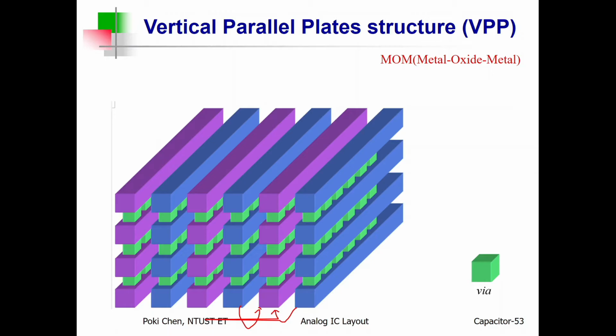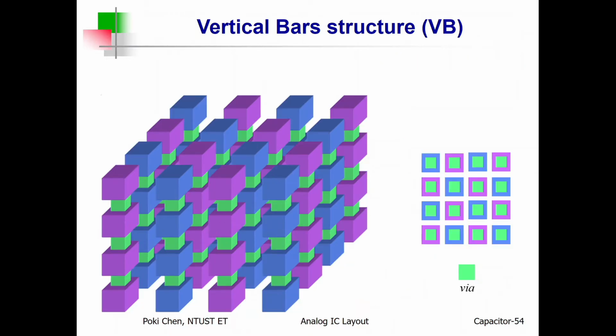Almost no electrical line will penetrate into the substrate or inject from the substrate. So it really means that the parasitic capacitance between the bottom lines and the substrate is almost nothing. It will be very close to zero. It is really good for circuit or RF operations.